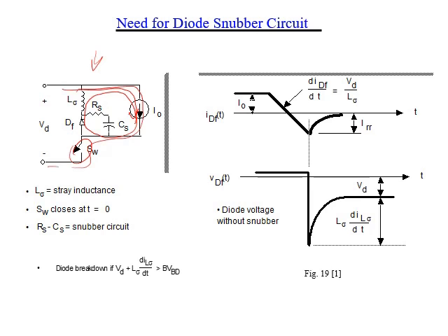Okay. Now we will put here, usually we assume, because we have wires, that there is stray inductance in the circuit. Okay. And we will put here a resistance and capacitor connected in series, in parallel with the switch we want to protect. Let me assume that I want to protect my switch, which is the diode here.